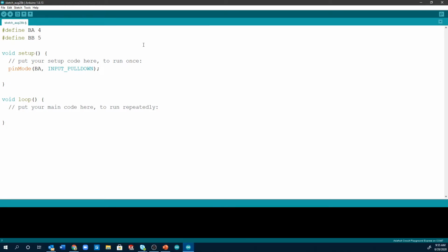Otherwise, the button just is not connected, and this can lead to small errors which will lead to the button thinking it's been pressed. Again, we're going to do this for button B, and we're going to use input pull down. By doing this now, the buttons will not be pressed when we are first powered up, and if you push the physical button, it will.